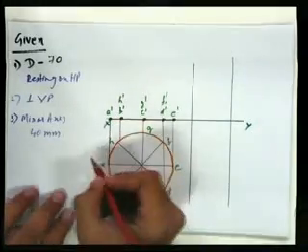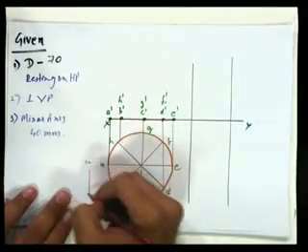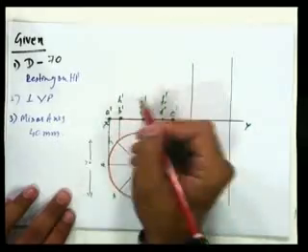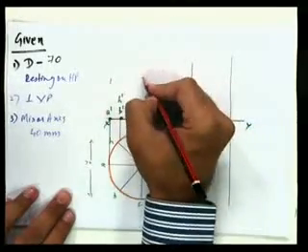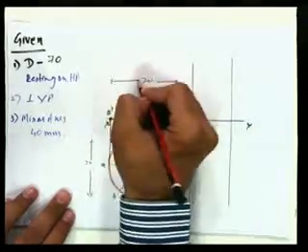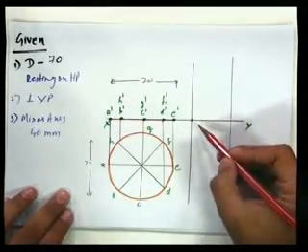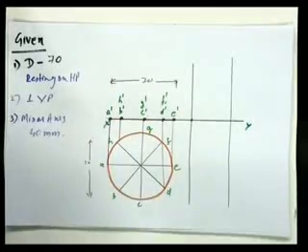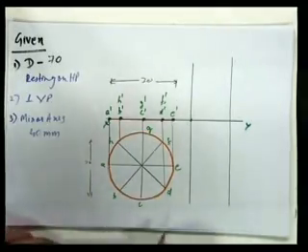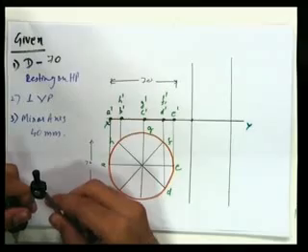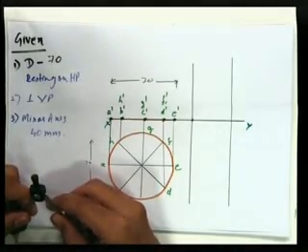Now here this diameter is 70 mm, hence this diameter is again 70 mm. So point A will remain here, and using my compass I'll take a 70 mm arc and cut an arc on the other line.